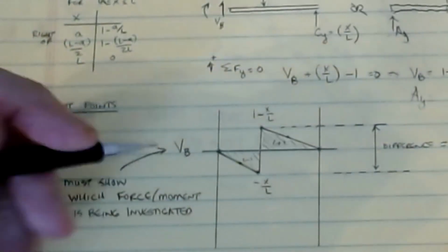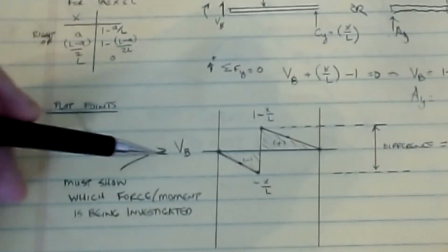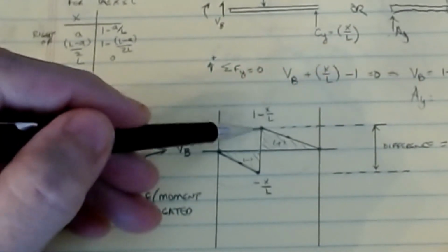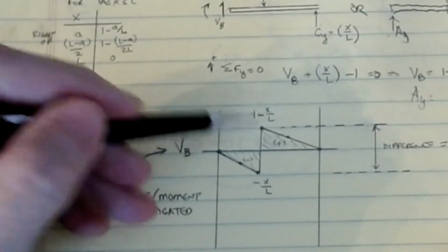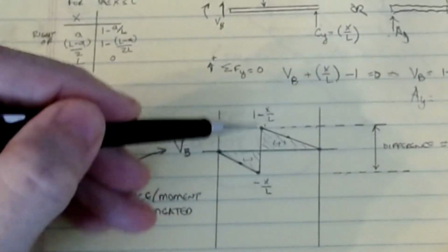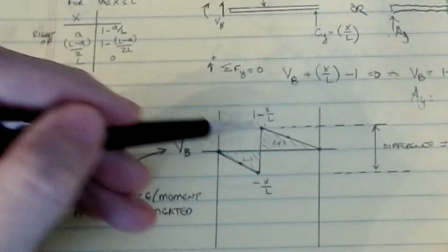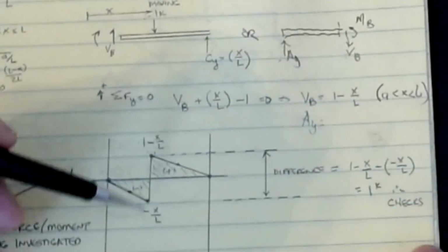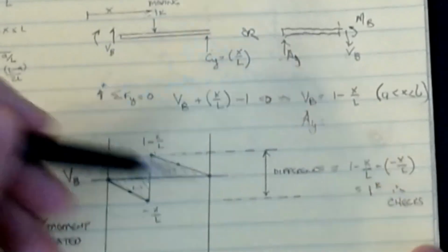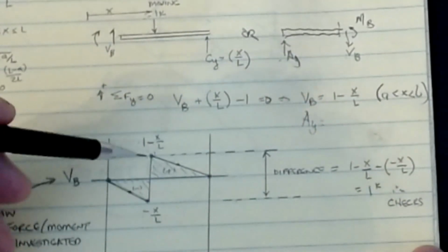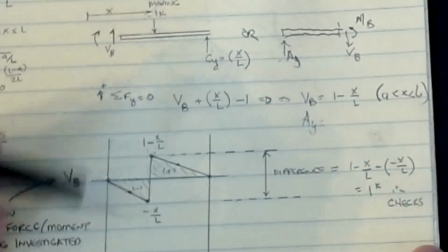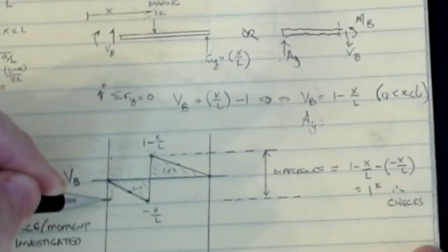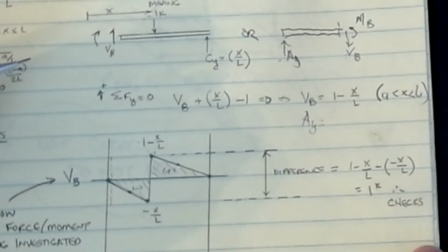It's interesting. This is the influence line for the shear at B. It basically decreases negatively until the point load is sitting just to the left of that point, I get this value, and as soon as I step over the point, it jumps. You'll notice that the amount it jumps, this difference here, is equal to 1 kip, the amount of the point load. So there's this instantaneous jump in shear. Shear diagrams produce some very interesting shapes. Now, suppose I wanted the shear just to the right of the support at A.